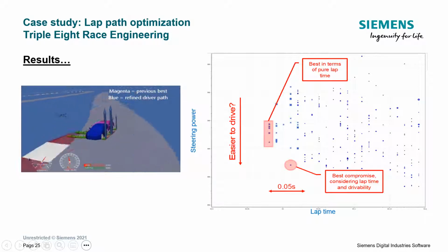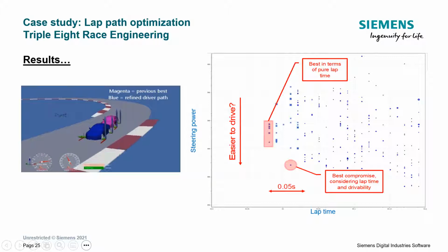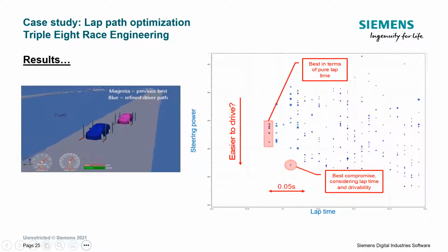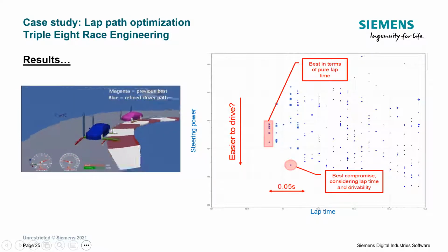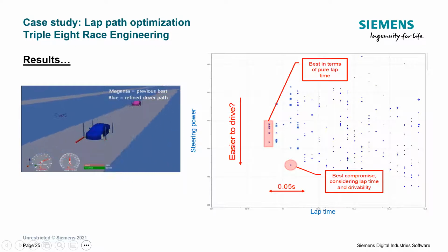Engineers then selected a design that represented the best compromise rather than the lowest lap time. In the process, they also determined that there were some curbs on the course for the driver to drive over, whereas there were other curbs to avoid completely. This approach helped them to achieve 4 pole positions and 12 first or second place finishes during the race season.